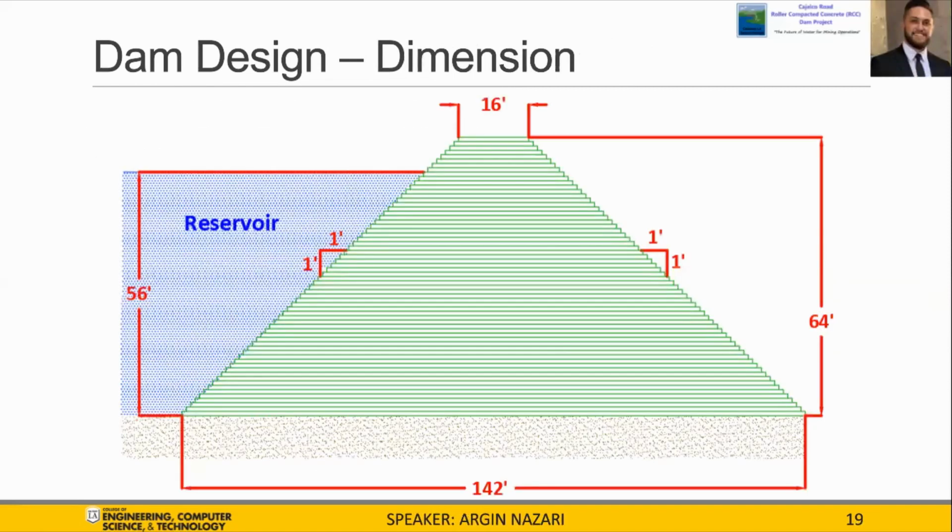As explained in the previous slides, considering the acting forces on the RCC dam structure, as well as analyzing the stability necessary to withhold these forces, we were able to determine the dimensions of the dam as shown in the slide. A wider dimension for the dam is expensive since it uses more concrete material. However, it will have a higher overall stability. For a smaller dimensional width of concrete, the dam will be inexpensive, but will compromise the stability. However, our proposed design fulfills both criteria of being soundly stable and economically efficient.